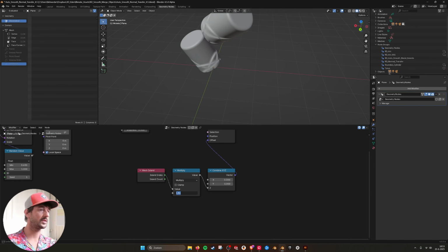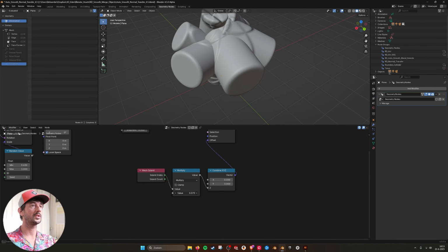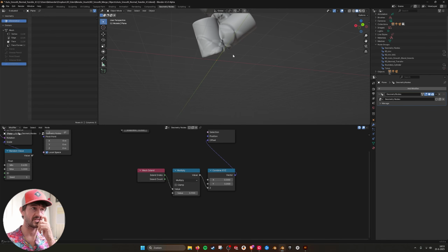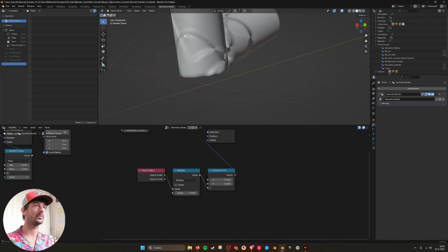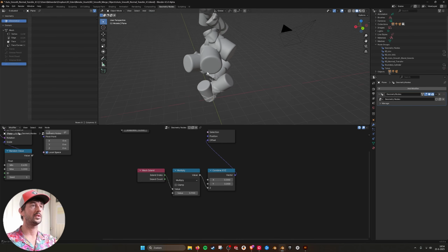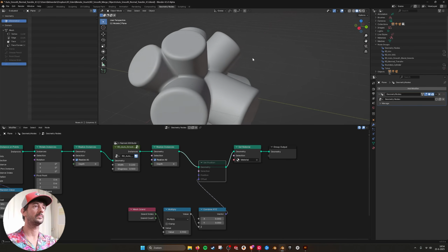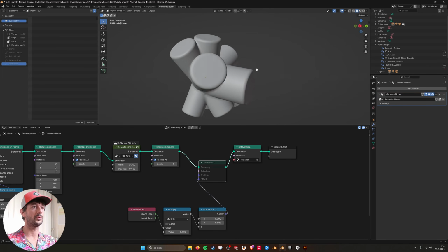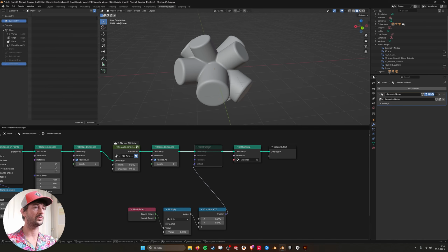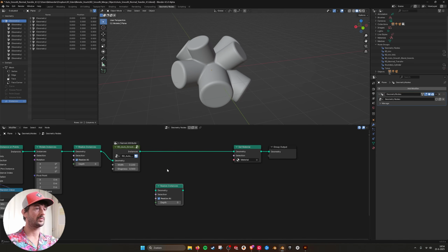So if I take this down 0.2, now I'm offsetting all these cylinders so you can see which normals are calculated. Here you can see that all the normals of the intersections are calculated, and now it looks a little bit weird. But if they are all set in the right position, you can see that it's correct. You get this very nice smooth effect without blending all these normals of the real faces. So offsetting the faces, but just doing it by the smoothing.